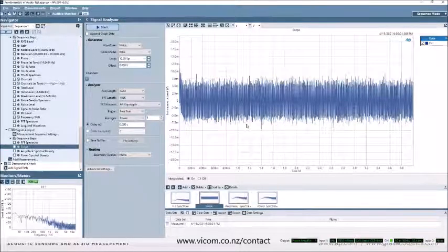Now, sometimes people want to have a signal that has various qualities of a noise-like signal, that is to say, a distribution of energy over frequency that represents random noise, but they don't want a very high crest factor, so they'll apply limiters or compressors or other filtering techniques. But all signals have a crest factor. That one's easy to answer. And noise signals, by definition, will have the highest crest factors of all signal types.